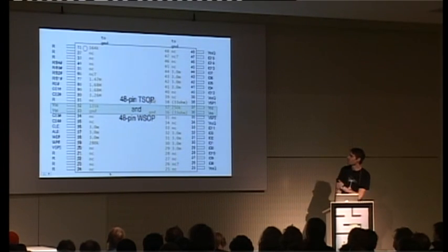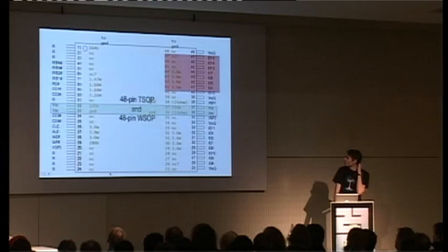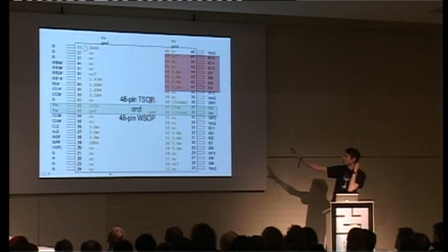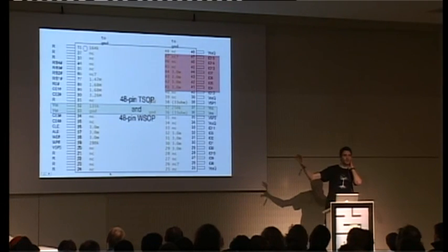So this is a 48-pin TSOP layout in black from the ONFI standard, and my electrical analysis in the orange. So here you see that ground and VCC might match, but what doesn't match is the I/O. In my case, some of them were not connected, or it seemed to be. So this particular footprint was for a 16-bit CFI standard.